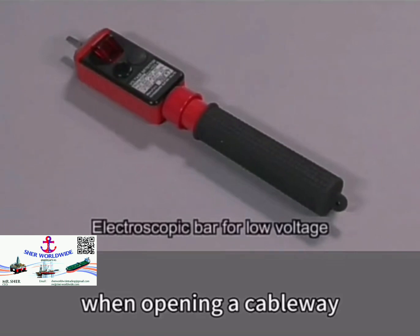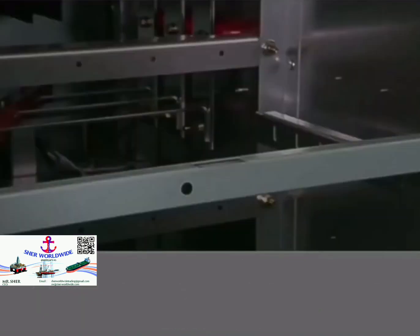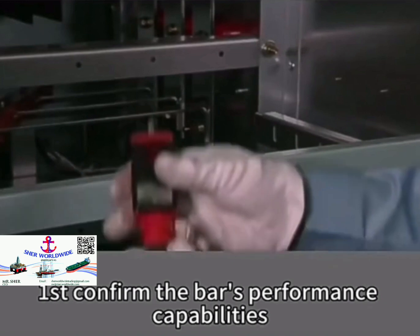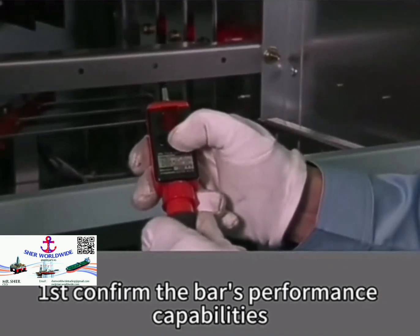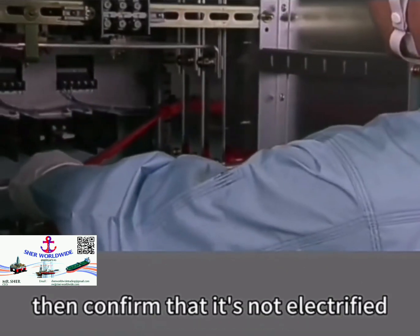When opening a cableway, use an electroscopic bar to confirm that the cableway is not electrified. First, confirm the bar's performance capabilities. Make sure that it makes a sound when electrified, then confirm that it's not electrified.